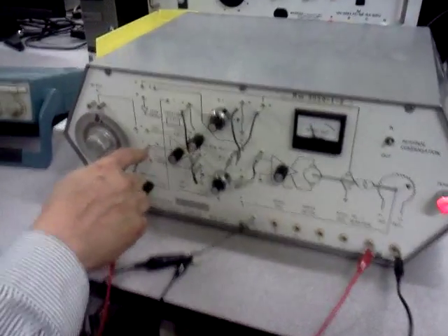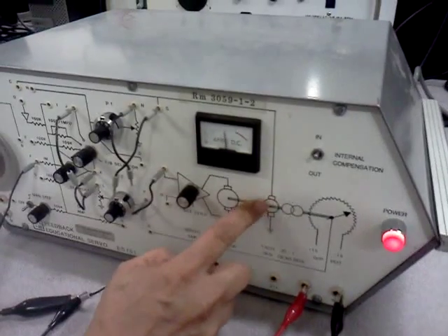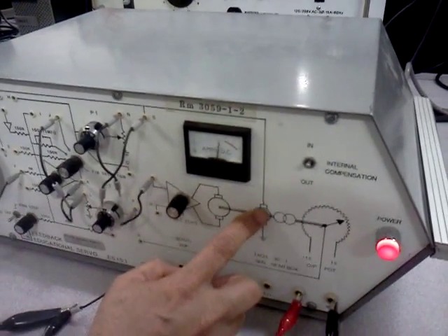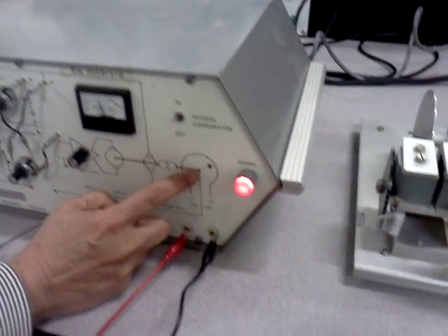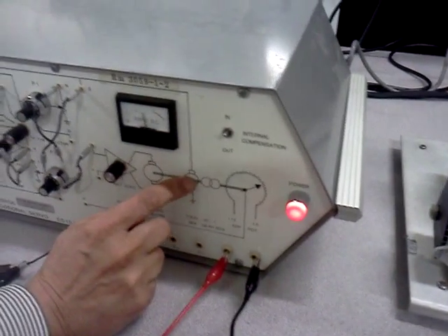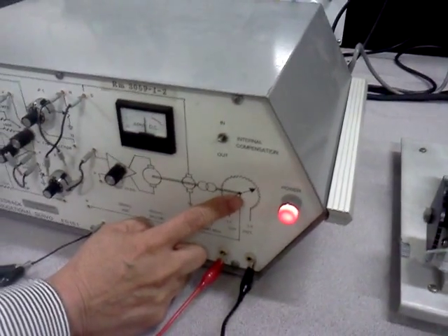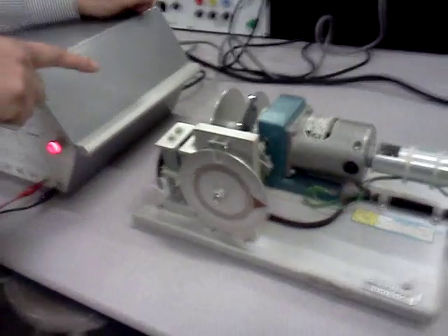Okay. So the sine wave goes in, and this will cause the speed of the motor to change in a sinusoidal fashion. And this will also cause the position to change in a sinusoid, because position being the integral of the speed, if this is a sine wave, this will simply be a cosine wave, so they'll both oscillate. You can see that here.